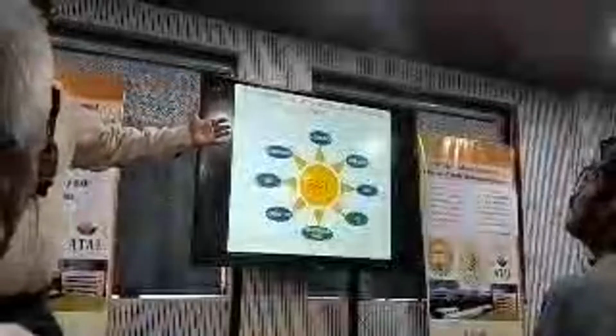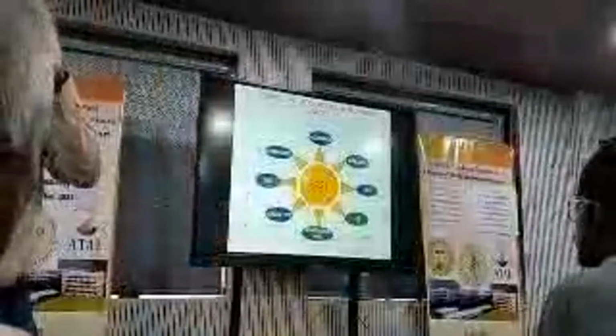So this is the gamut of total signatures of any ship and submarine, like the acoustic signature, whatever I discussed, the noise levels, and infrared signatures like temperatures, because we have the exhaust temperature from the ships. It is emitted from the engine room through the exhaust funnel. So we will check the temperature of the exhaust, and the temperature will be identified. If it is above the ambient temperature, he will think that maybe an enemy ship or enemy submarine is coming. So we have to reduce the IR signature.